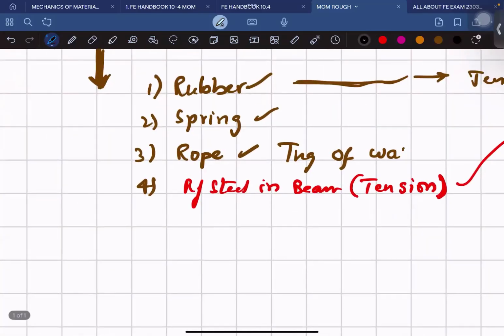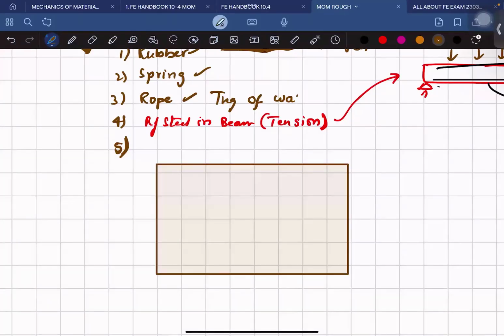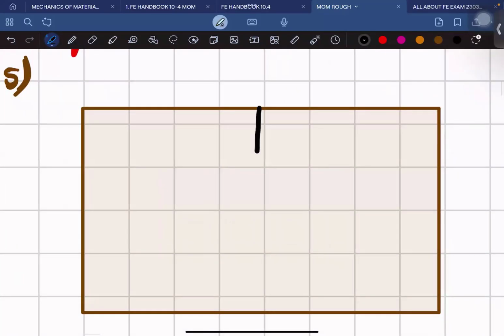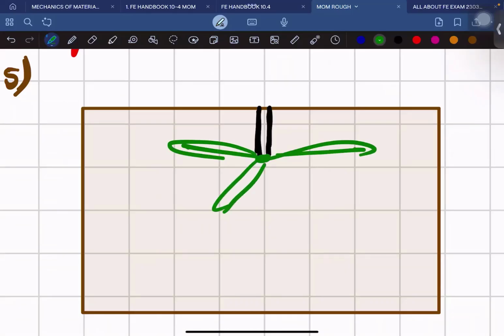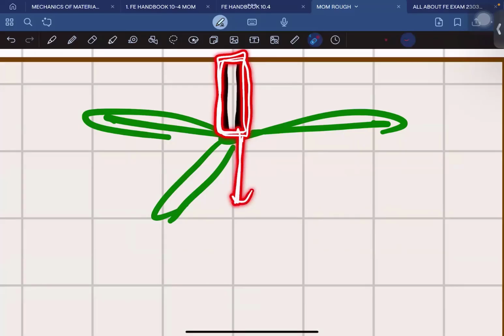Even you can notice you are staying in your room now listening to the class. Does your room have a ceiling fan? Yes. So you have a ceiling fan, and from the ceiling the fan might be suspended by some steel rod, and you might have hung the ceiling fan like this. Because of this dead load of the fan, tell me, does this rod undergo tension or compression? Tension. Yes, this will be under tensile force.